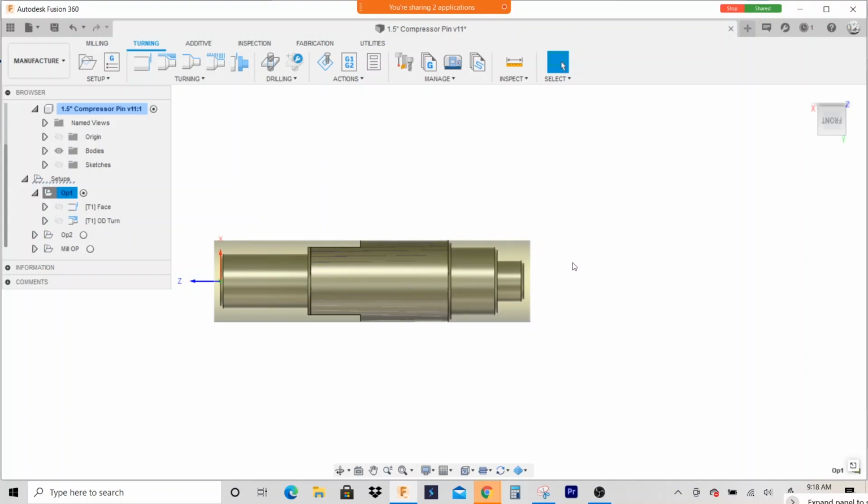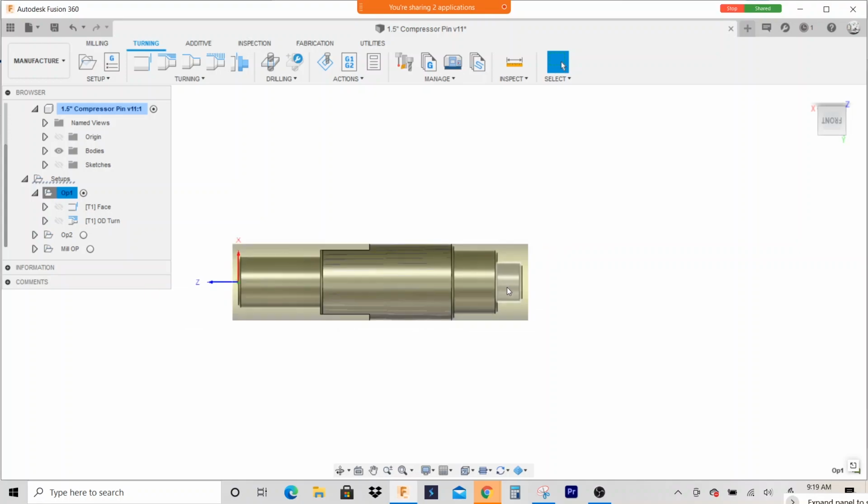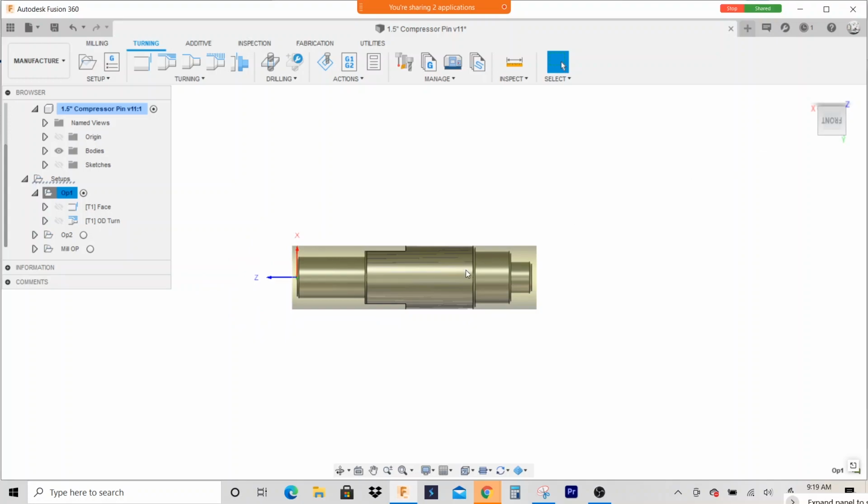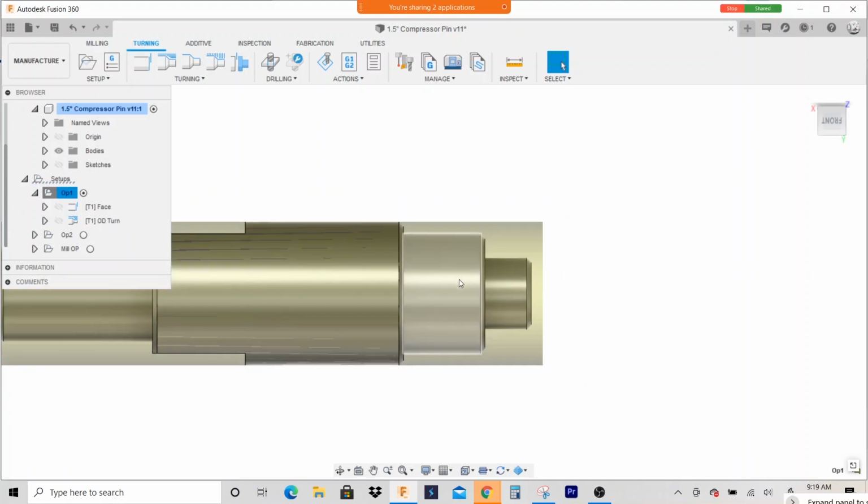Then I have a turning template, which is just a canned cycle. It's a G71, and basically I have all these templates on there. So sometimes it makes sense for me just to copy and paste a G-code script, and just change the starting and ending positions, because I can literally do that faster than jumping on the CAD cam and drawing the part, doing the setup, creating the toolpaths, posting the code, saving it to the USB stick and putting it on the machine, all that. If it's just one simple part with a couple of turned ODs, I don't even write a program, or I'll just handwrite one.